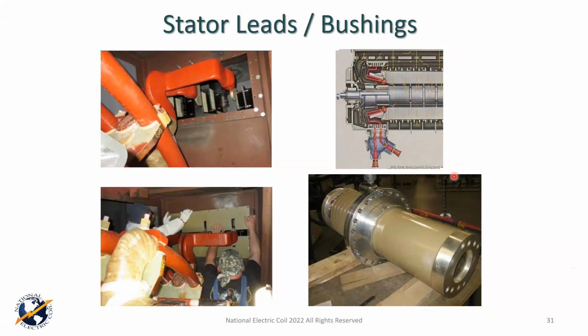All right, we're almost to the end of the stator here, and the last real stator components I wanted to talk to you about. We got the electricity inside the winding, goes out the end windings. We got the phase leads that go up to the phase rings. Now we got to get that power from the phase rings out to the isophase and out onto the GSU and out onto the grid.